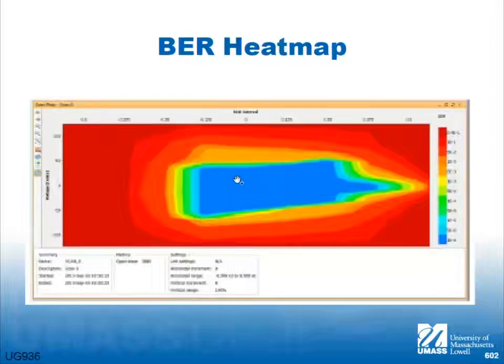During this area right here, you have the highest probability of detection, right? So if you're sampling right in the center of this area, you're going to sample true data. As you move to the edges of this, you're likely to sample in a transition and get wrong data. This isn't a class in bit error rate testing or communications, but that's what this does. So suffice it to say that there is other internal test equipment on the FPGA.